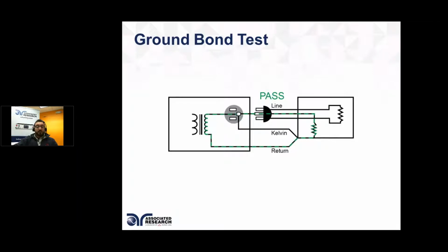because we know when a ground bond tester injects current into the ground pin, there's also a voltage. Obviously you have to have some voltage to be able to inject that current, so that voltage level is usually less than 12 or 8 volts. So very low voltage and high current test, this one. And so as a result, the voltage drop occurs in the ground circuit, and that's used to calculate back the resistance of the ground circuit.